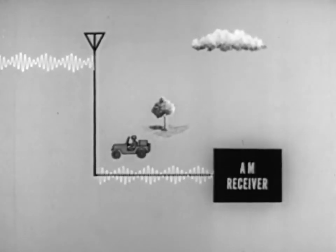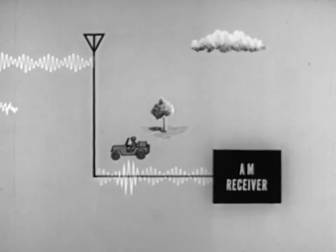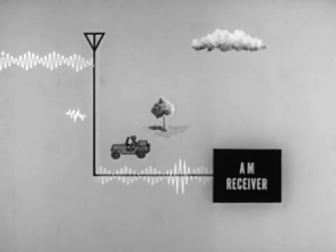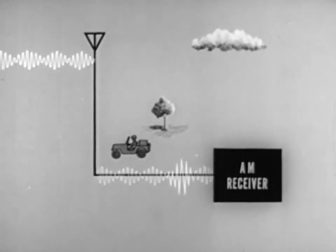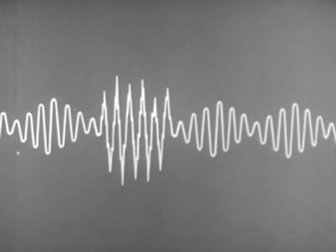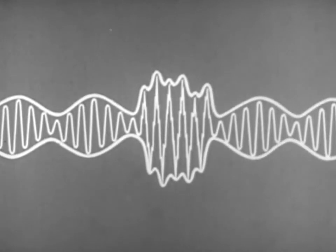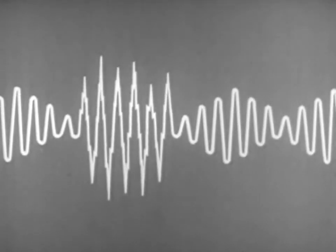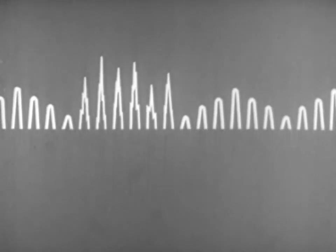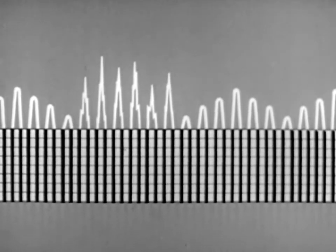There are many man-made devices and natural elements or occurrences that can affect the amplitude of the RF carrier. Each one adds more hash, more static, more interference. Before considering the AM receiver, notice one fact. The electrical disturbances alter the amplitude of the RF, but they have no effect upon its frequency. An important point to remember is that the distance between each wave is identical.